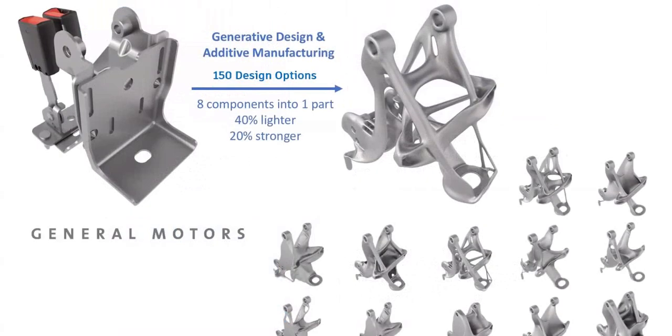So to take a look at what some of our customers are using generative technology for, this is a great example from General Motors, and I'm sure many of you have seen it as well. GM took this conventionally produced seat bracket assembly that you see in the top left of this slide, and they started to generate options to consolidate that 8-part assembly into just one single component. Eventually they were able to generate that assembly from 8 parts to one. The generated part is also 40% lighter and 20% stronger. And probably more important than anything that we've talked about so far is that they not just generated one single option, they generated 150 viable options that they could then start to explore and make trade-offs from.